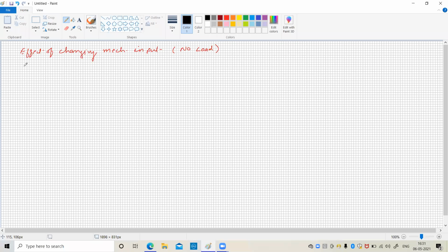means it comprises resistance, impedance, and excitation EF1 with ZS1, and this is the second alternator, ZS2, with excitation EMF EF2, and both are in parallel, again under no load condition. Under the no load condition, the terminal voltage is VT. So the external circuit and internal circuit are the same.